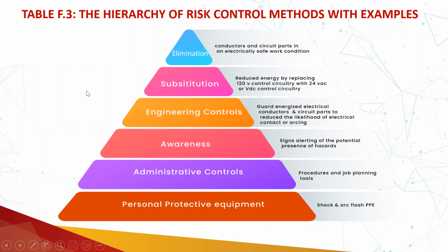In engineering control, we are putting some barrier, or creating some gap between the source of the hazard and the employee who is performing the task. So engineering control could be using a long handle voltage tester, or arc blast windows, or other openings or windows to verify whether the contacts have opened within the circuit breakers, rather than opening the panel itself and then viewing whether the contacts have completely opened or not. That will also fall under engineering control.